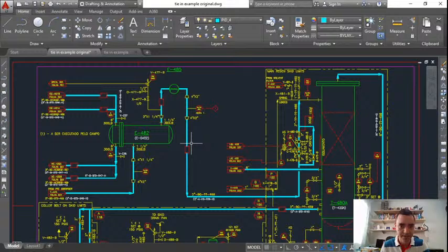And here between this heat exchanger and this observer, in this process, I need to add another equipment. I need to add another heat exchanger, and to do that, I will need to identify the tie-in points in order that the pipe engineer is able to go to the isometrics or to the piping plan and verify where he or she needs to cut the pipeline. So how will I address that in the pipe instrumentation diagram?